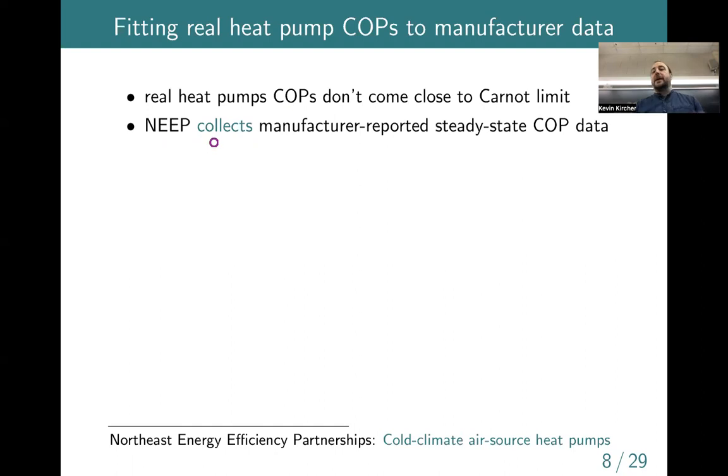So basically they make spec sheets. So when you're trying to choose between two different heat pumps, they can say, here's how big it is, here's its heating capacity, and here's how efficient it is. And so you get the cost and you get the efficiency, and you can compare between units and make a trade-off that works for you between the initial cost up front. Typically a more efficient piece of equipment is going to cost more up front, but it'll save you money long term and stuff like that.